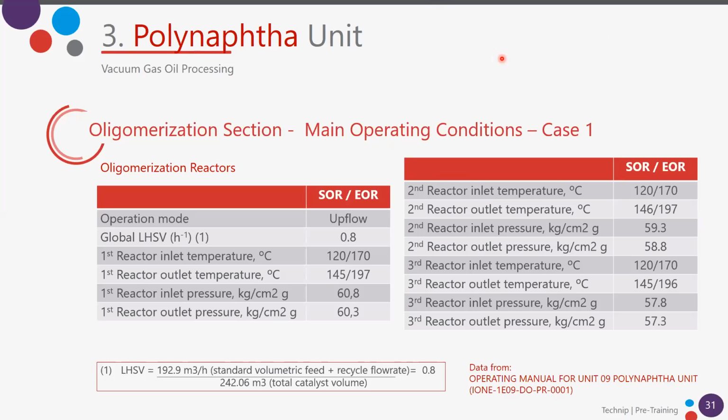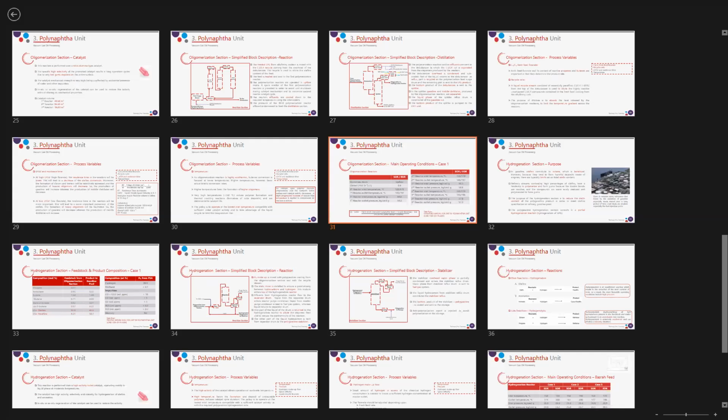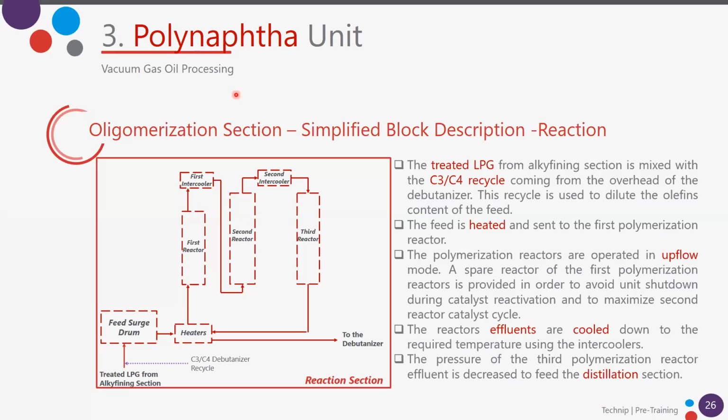Yes, you decrease the temperature. Remember that we have these intercoolers. We have to cool the outlet from the first to reach the adequate temperature for the second, and also for this.